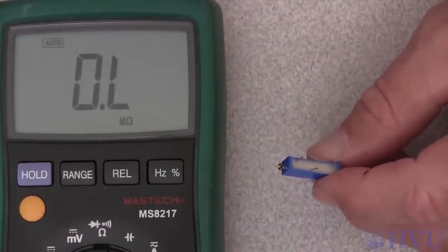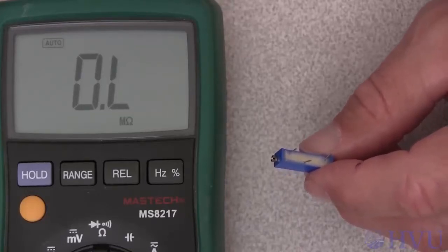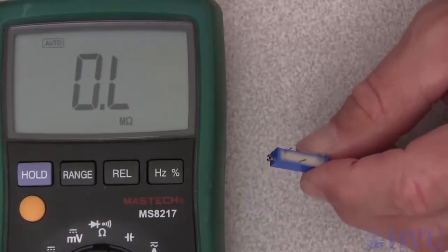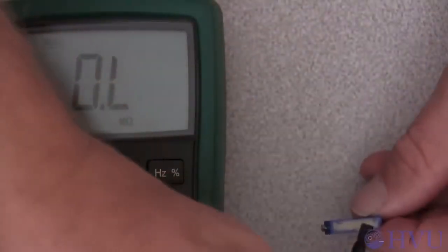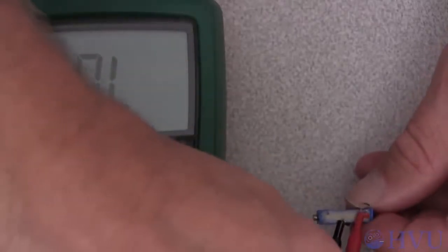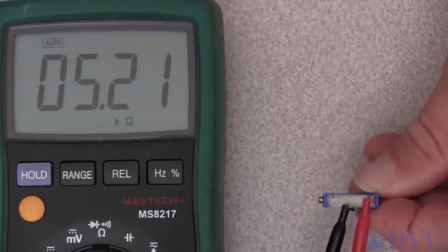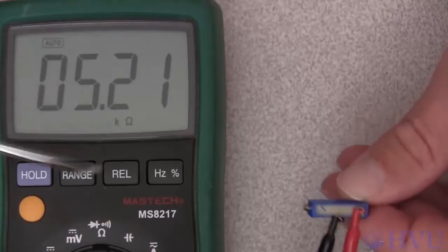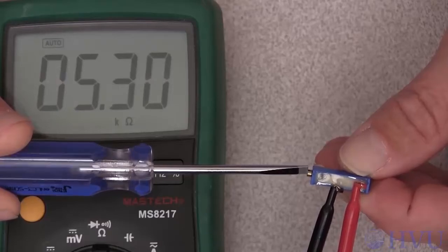Typically, we measure resistance with a digital multimeter, or DMM. Let's do that now and see how the resistance changes. To measure resistance, we set the DMM knob to the ohm symbol, plug the leads into the volt, ohm, and COM terminals, and then connect the leads to the resistor pins. I'll use the center pin and this outer pin. Currently, this resistance is about 5.2 kiloohms. If I change this screw position, the value of the resistance changes.